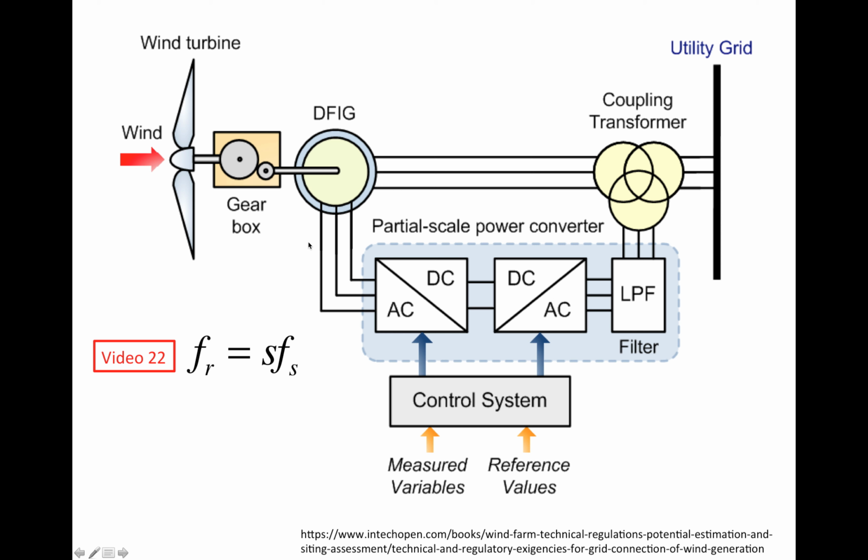the power converter appears as an external resistor. The voltage across these terminals and the current across these terminals are going to differ in phase by 180 degrees, just a minus sign, because the power is flowing out. Otherwise, it would be in phase if you did not account for this change in sign. So it's going to appear as an external resistor to the rotor, right?